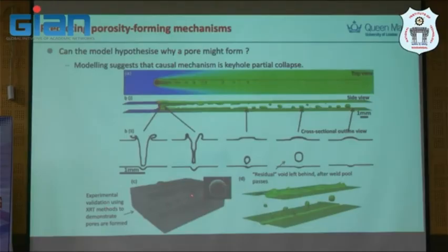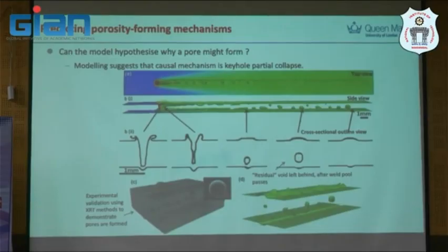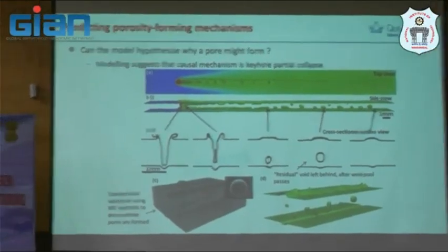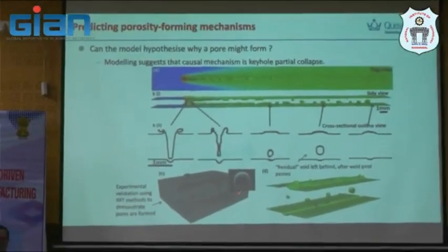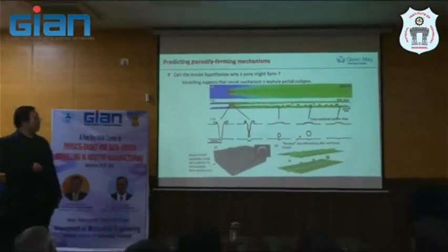Having said that, not every pore is spherical, because for titanium, using micro CT, we cannot map every single pore here, as we were limited by resources at that time. Now you can see more if you use neutron tomography, which may be able to reveal all the porosity content inside, but resolution is another problem.